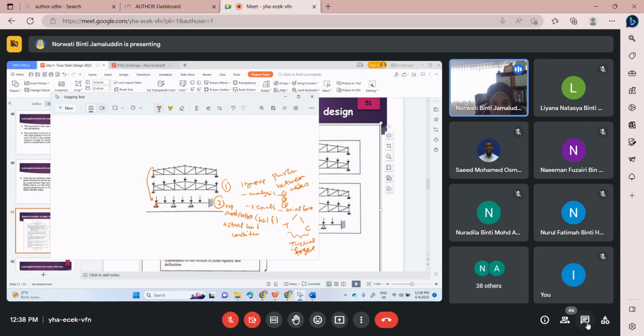Because the purlin is supported by this one. This is support. At knot is assumed as a support. Okay. So first purlin, second purlin here, the second one, the third one. See? This one on knot, this one between knots. Number 5, number 6. Okay, and then that's all. When you consider half, of course, you need to consider that as a fixed joint.